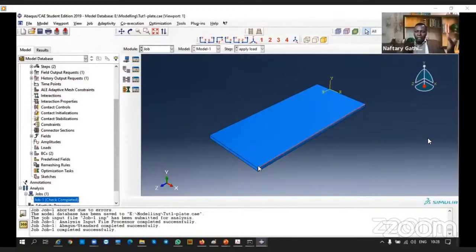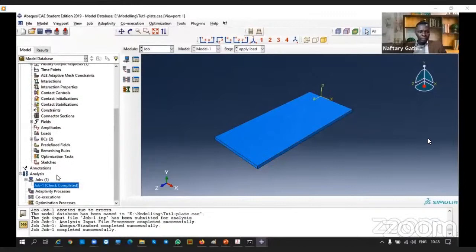But when you have different parts, and for your analysis, you might have 2 parts, maybe for the 4-point loading. When you have those loading points, you define using a rigid body so that they do not deform. But it depends with how you want to apply the load. So it's telling us our model is okay, and we can submit it to analysis.